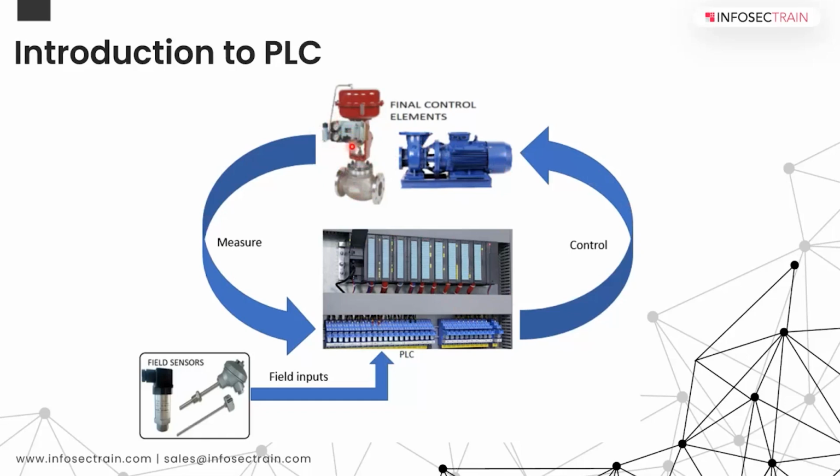For example, if it opens or closes, we know there are limit switches here, or sometimes it could be a smart transmitter as well for the position. So it could be analog, it could be digital. This input is given back to know the status, like for example, this is on or off or closed or open.